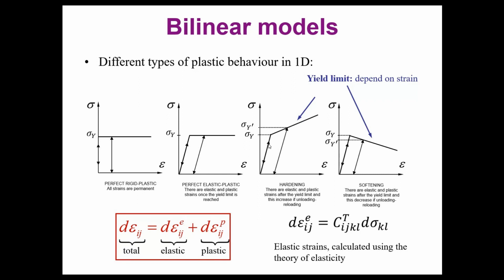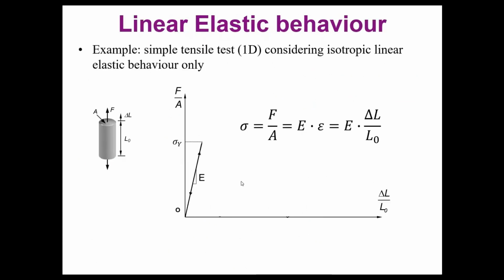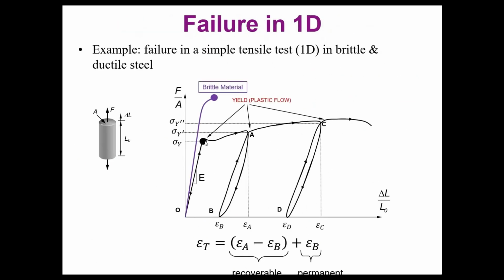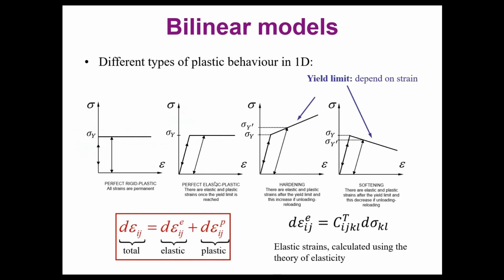So in this unidimensional model, it's relatively simple to define the failure, because we are saying this is our limit. As we saw before, if you remember, when we started this definition, the failure is defined when the yield strength is reached in a ductile material. So when we do that in a one-dimensional model, it's very simple, because in this case and in this case it's just a value which is constant, so super simple.